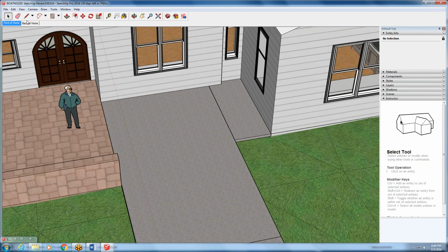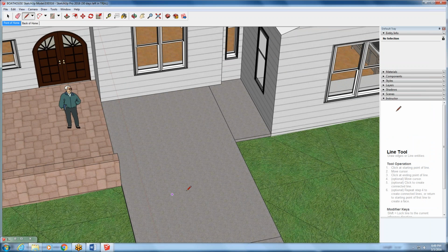So supposedly what you're supposed to be able to do is, if you create a line to begin with and you end it and then you type in 3, or let's do something bigger, 6 foot, enter. Okay, that's what I was trying to do. I have no idea why it wasn't working in the other drawing. I'm sorry for that technical difficulty. But you can type in the distance after, say you're like, oh no, I drew that a little bit too short, I'm going to retype in the actual distance I want. Then it adjusts the line or shape scale for you. So that's kind of different from AutoCAD. Once we've drawn it in AutoCAD, we have to delete it and start over or stretch it and pull it by its pick points.